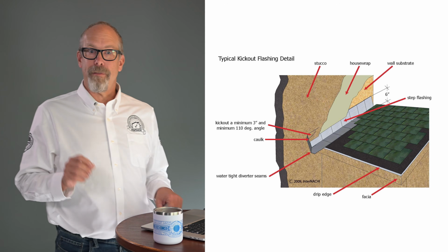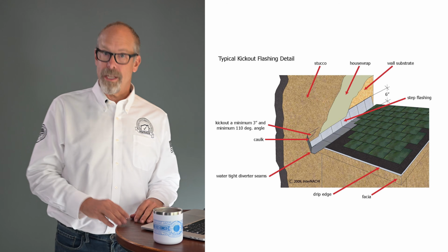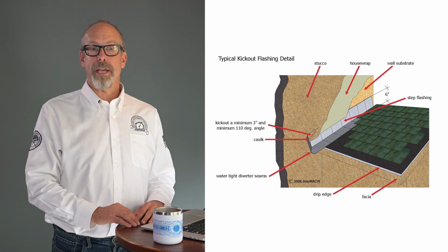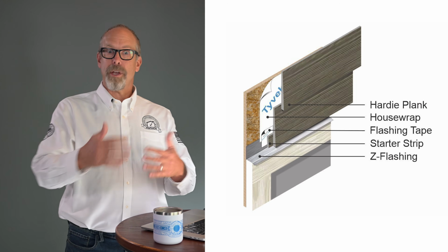This single detail prevents some of the most severe localized moisture damage when properly installed, but causes extensive problems when missing or incorrectly installed. Flashing effectiveness depends on proper installation, the sequence of the installation, and the integration with the weather-resistant barrier, the WRB. And the materials must be layered correctly so that water flows over each component toward the exterior. Poor sequencing can create water traps that cause more damage than having no flashing at all.